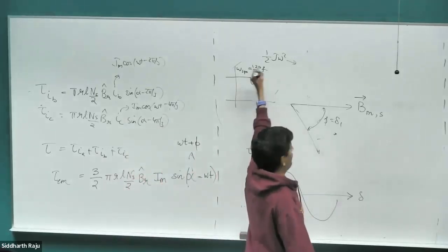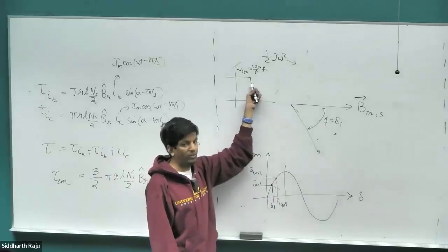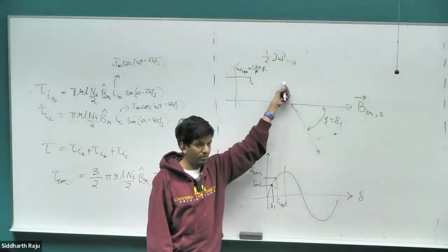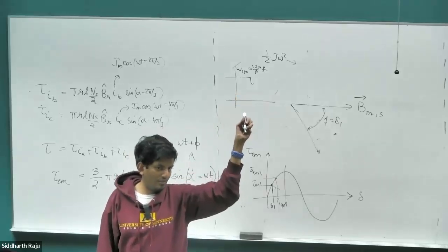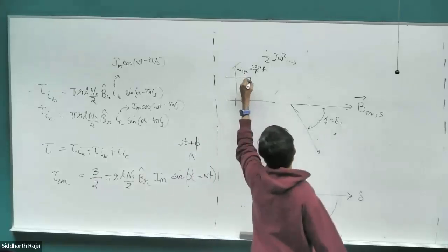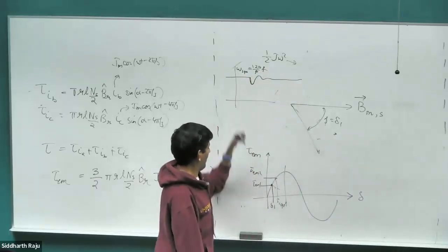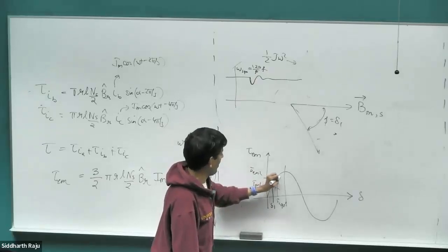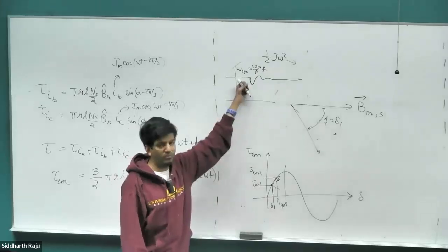Alright? What will be the speed once it reaches steady state? Will it go to a reduced speed and stay there? What is the name of this motor? Synchronous motor. So the speed would have to come back up. So it would execute a nice oscillation, it will come down, go to a little bit higher load angle, come back, and settle down to this new load angle. But the speed would always have to be synchronous speed.